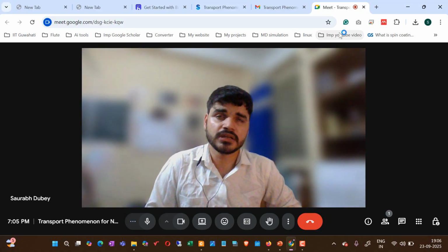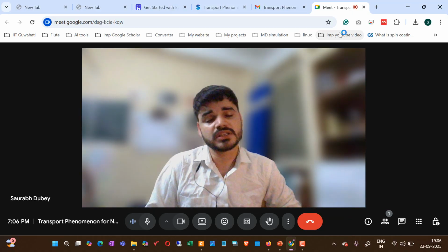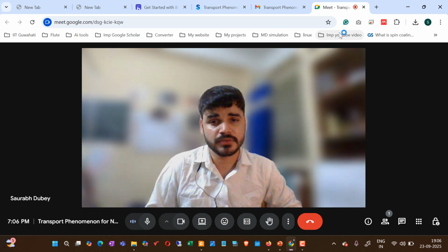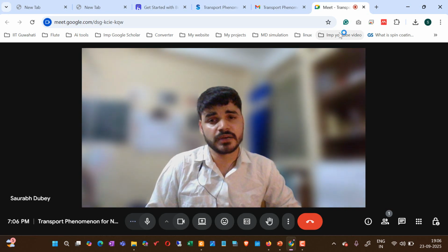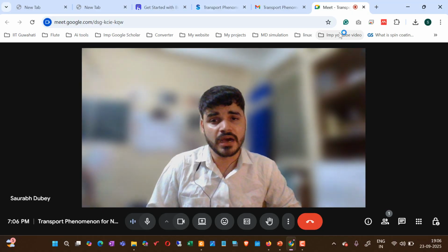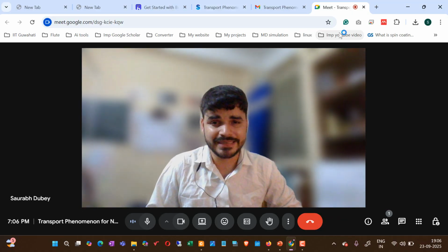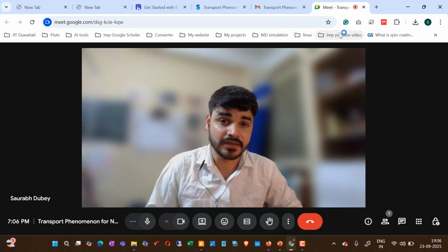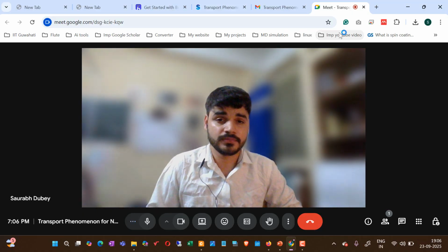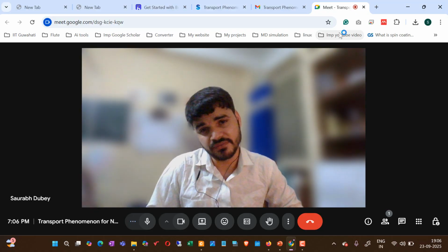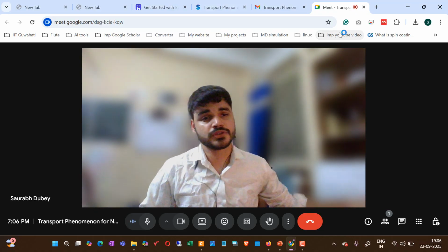In the third lecture, we were looking at a spherical particle, how mass transfer happens with momentum transfer, and if thermal effects are also there with the diffusivity, how the entire transport phenomenon will be modeled. For example, if the surface of the sphere is a catalyst, then there will be a reaction on the surface. So how this reactive species production or consumption is related to the temperature, and at the same time to the fluid flow?